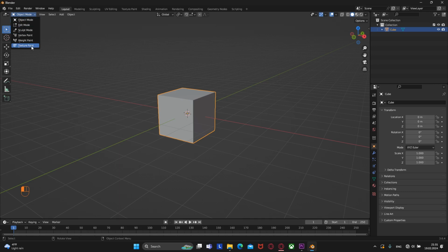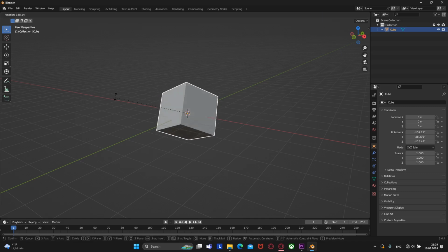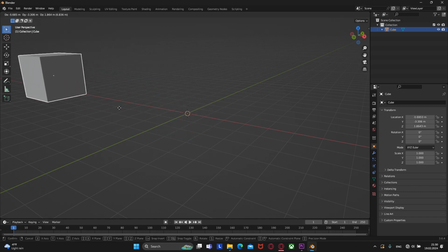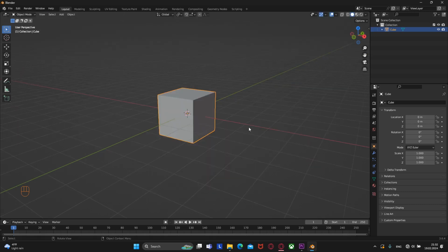Blender also has modes that you can choose here. And as you can see, there are a lot of them, but today we will analyze only two of them, the Edit mode and the Object mode, in which we are by default, and which allows us to select different objects and make changes that I mentioned earlier. As Edit mode is intended for more detailed changes to the object. To go to the Edit mode, we need to press Tab.